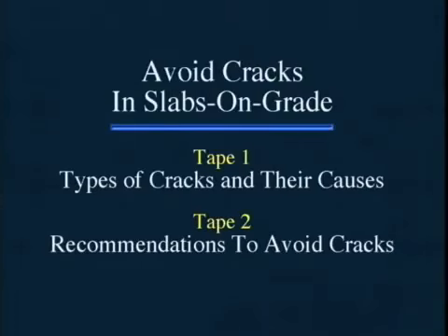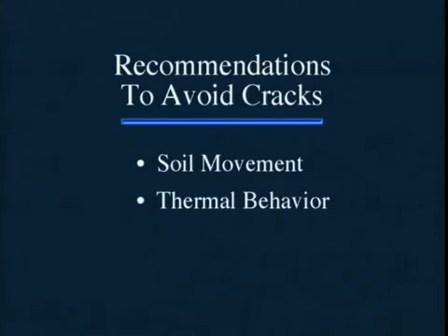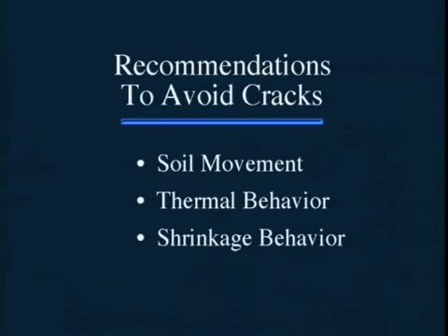Here is an overview of avoiding cracks in slabs on grade. Tape number 1 covers the various types of cracks and their fundamental causes. Tape number 2, this tape, covers recommendations to avoid these types of cracks. Under recommendations, I'll discuss how to avoid cracks from soil movement, thermal behavior of concrete, and shrinkage behavior of concrete. Let's start with soil movement. I'll cover soil heave and settlement.